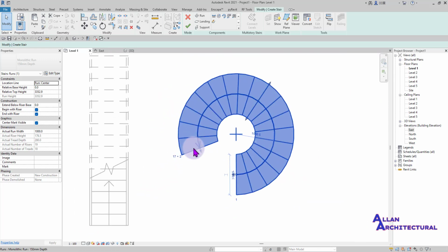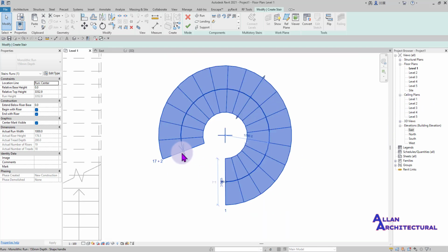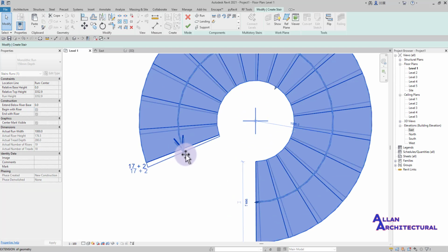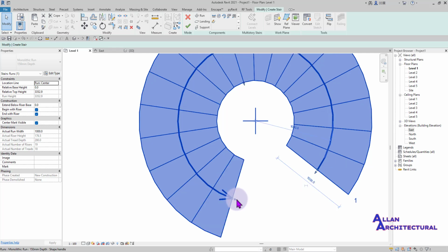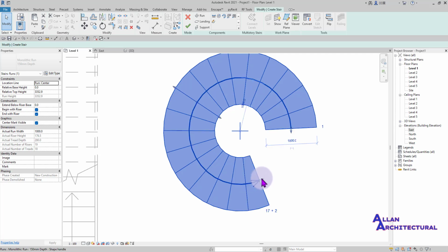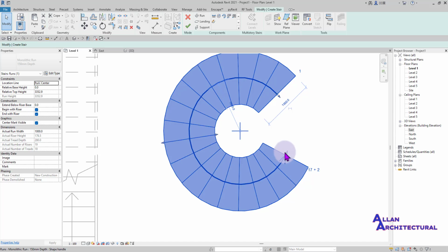And if I should finish this, Revit is going to give me a warning sign that I'm going above my building regulation in there. All right, it's not going to fit from level 1 to level 2. So we have that in there as well. And then when you click on this arrow right beside it, it's actually going to move the entire staircase. All right, it's not going to add rises. When you click on that arrow in there, it's just going to move the entire staircase, and you can move that to fit to the orientation of the particular stair that you want.